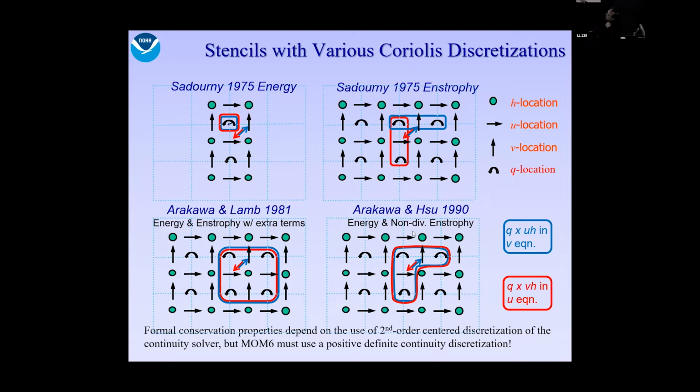The red arrow and the blue arrows are connecting adjacent u and v velocity points. There are four northward velocity points around each eastward velocity point, and conversely for the other terms. Here I'm just highlighting the stencil of the potential vorticities that are connecting these two adjacent velocities. Recall that there are four of these that contribute to this u velocity point. And the size of the stencil here is everything that will contribute to that u velocity point or that u velocity point contributes to.